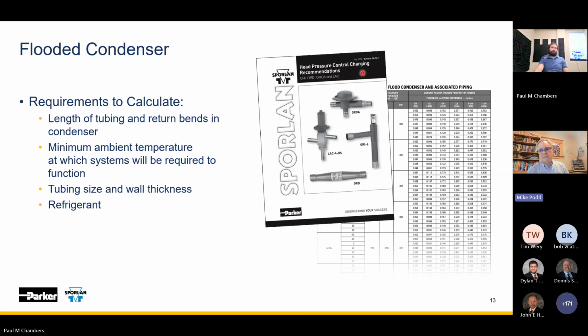So what dictates your pressure settings is your design ambient conditions and the saturated pressures at those conditions. So you can pretty much determine if we're going to be working at 90-degree condensing, I should have mine set for a pressure corresponding to that. So our factory set, like the 180, is a fairly common setting for basically the R22s, the 404s, and 448, 449 are very similar.